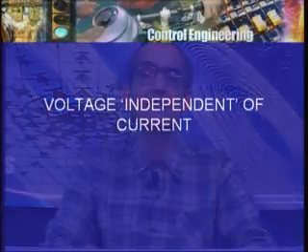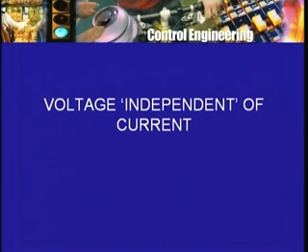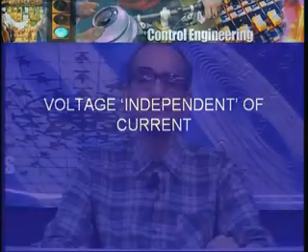So that is something which is not written here when I write V equal to E of t equal to 1.5. The claim is that this cell or battery will be described by this no matter what current flows in it, what value of current, and whether any current flows in it or not. Now that's certainly not true of a practical cell. From this small cell, you should not draw perhaps a very large amount of current. Its voltage will no longer be 1.5 volts. Not only that, the cell can even get ruined.